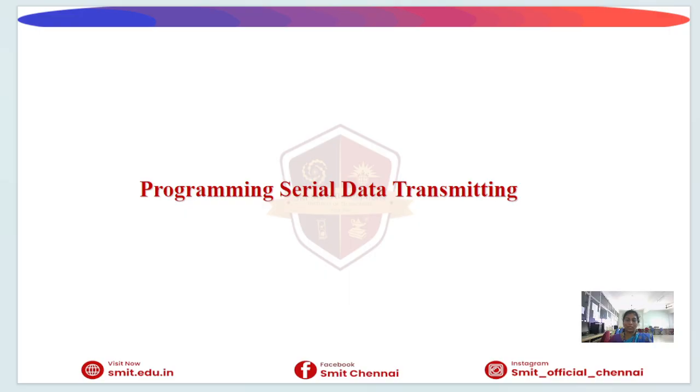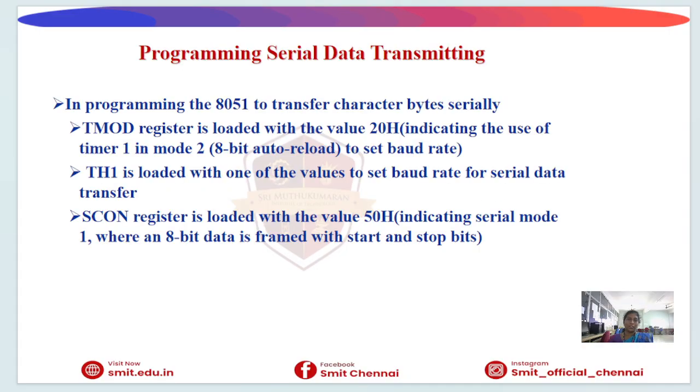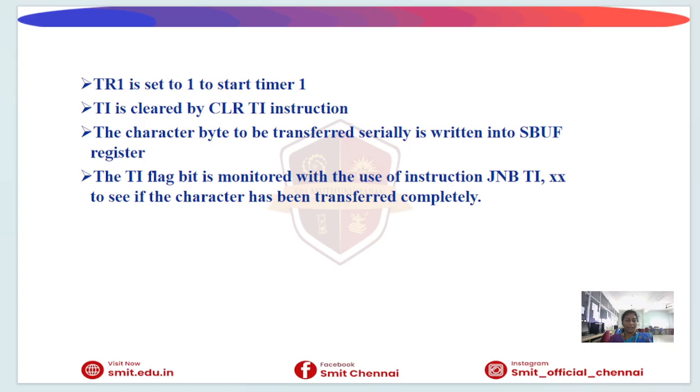The microcontroller uses registers such as TMOD, TH1, SCON, and SBUF. These registers help in setting the baud rate, selecting the communication mode, and transferring the data. So, what are the steps for programming the serial data transmission?